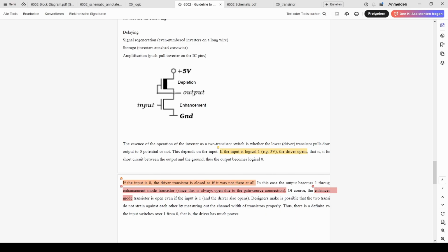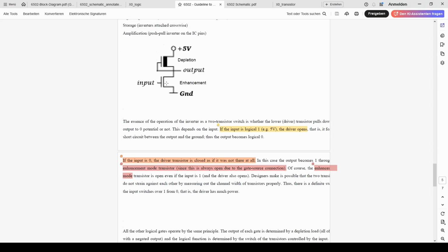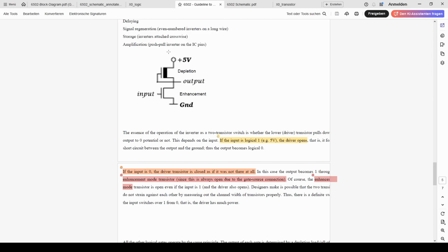And in fact, apparently the 6502 actually does use this also in other places. A depletion mode transistor with a connected drain and gate is called a diode connected transistor, and it basically just acts like a resistive load. So, in a nutshell, this is what we consider a pull-up. Or we could consider this just a pull-up resistor. For our purposes, it doesn't matter.